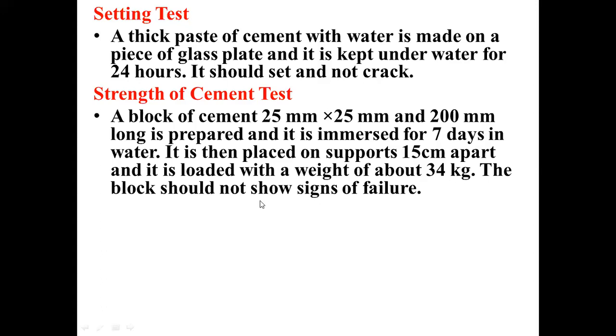For this we are going to prepare the cement mortar mold. In the previous case, the setting test, we prepared a paste, but here a mold is going to be prepared, and we are going to test it after 7 days with a load of approximately 34 kg. It should not show any failure or any cracks on the mold. So that is the test we are going to conduct.